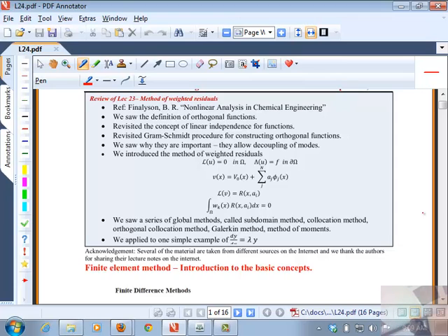One of the things in fluid mechanics, for example, is you have the Navier-Stokes and you have the continuity. So you have to propose a test function for P and a test function for V. If you can propose a test function for V that automatically is divergence free, that's a keyword that they use, that means the functions that you're putting into your test functions automatically satisfy del dot V equal to 0.